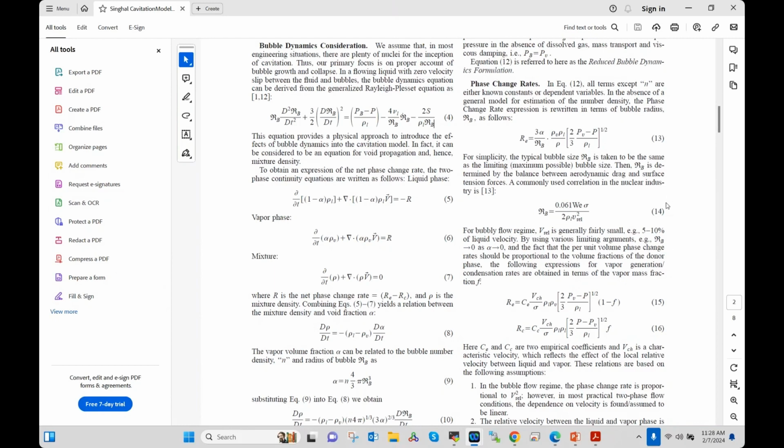The next question from Gabor Lechner is, how is impeller blade surface roughness taken into account in cavitation? Right now we have a roughness on the surface. You can provide a roughness height, but this is not taken into account explicitly. It's just a term in our flow solver. So in the cavitation model, it will be affected based on how we solve the flow field. That's what I would say for this question.